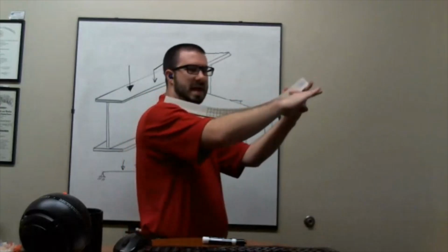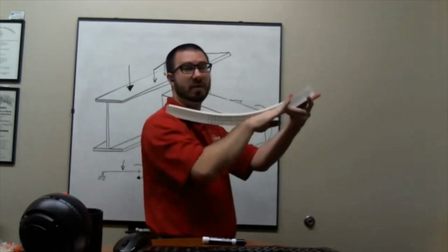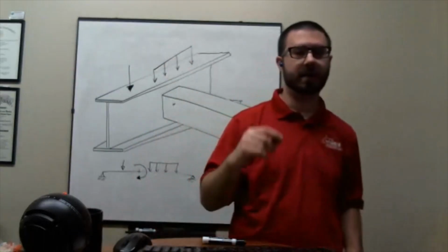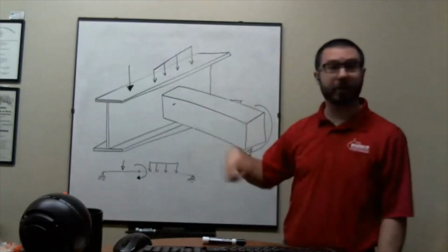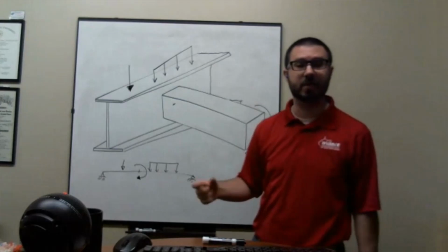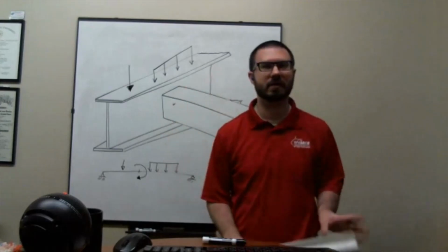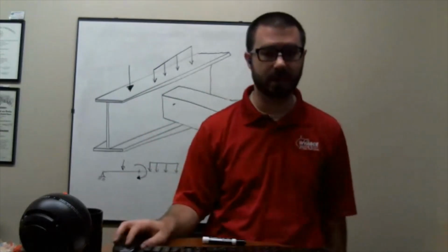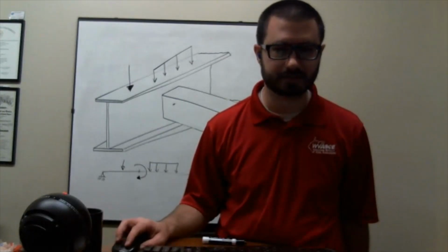You can see here that, as the beam deflects, the beam was flat and now it's not. So it has an angle change to it as well. It goes down and it changes with its angle. That angle change, we call that a rotation. And in order to determine rotations later on, we're going to apply concentrated moments. So we need to be able to handle these, not just from a physical perspective, but from an analytical one as well. Now, let me go back to my slides.